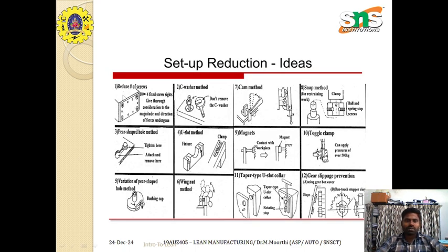Setup time reduction starts with the idea. During the process we will get n number of ideas, and some of them are reducing screws and the C-washer method. These are a few examples.